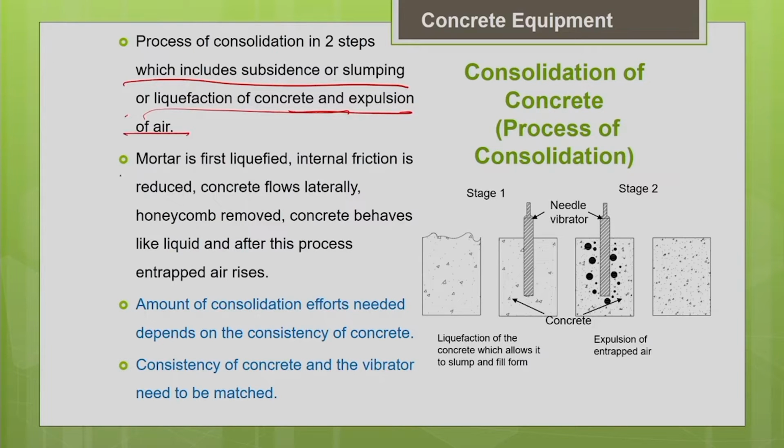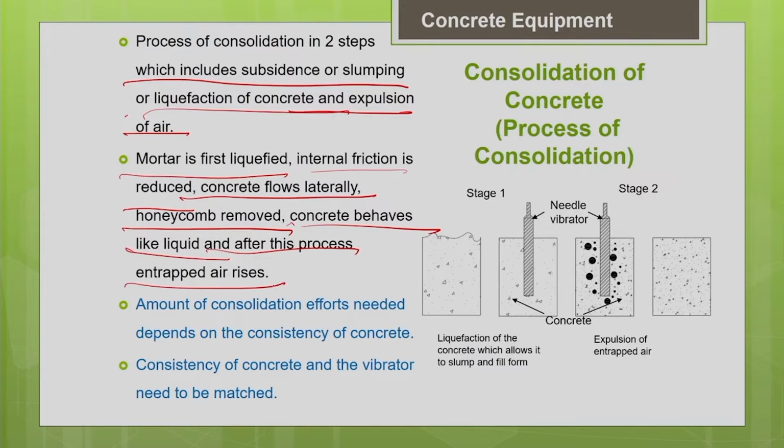The mortar will first be liquefied. The internal friction is reduced because of the vibration, and the concrete starts flowing laterally. Any honeycomb that is there in the concrete will be easily removed. As I told you, the concrete behaves like liquid and fills the formwork. After this process, you can see that the air will rise to the top. Your entrapped air will rise to the top surface of the concrete.